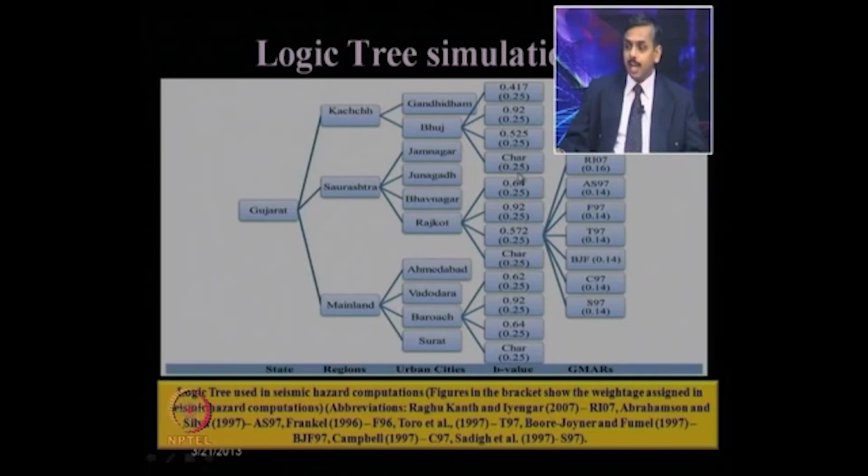Let us give equal weightage to all of them. As I said, it is the designer's choice, or based on the experience or knowledge of the area or the earthquake analysis and study, etc. So, we have given an equal weightage of 25% to all these 4 seismicity models.